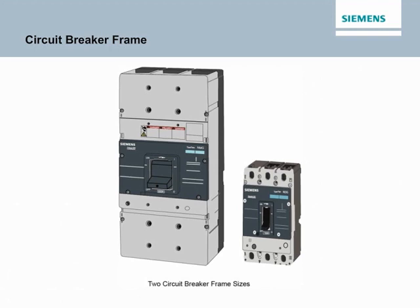The frame provides an insulating housing to mount the circuit breaker components. The construction material is usually a thermoset plastic such as glass polymer. The construction material can be a factor in determining the interruption rating of the circuit breaker. Typical frame ratings include maximum voltage, maximum ampere rating, interrupting rating, and physical size.